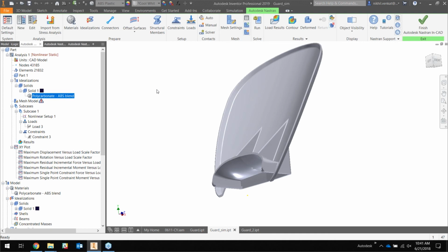Got it. I think this is the last question, if I'm not mistaken. Oh, sorry, two more. Would you recommend using nonlinear analysis when looking at high loads being applied over small areas? Yes, because that's the very definition of buckling. So for sure, I'd look at nonlinear and do a buckling analysis as well. Buckling analysis will give you the eigenvalue, which is essentially a buckling load factor. Based on that, it's going to tell you if it's actually going to buckle or if it's just going to fail. And based on that, you can decide if it's linear or nonlinear.